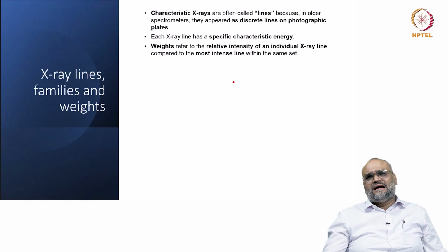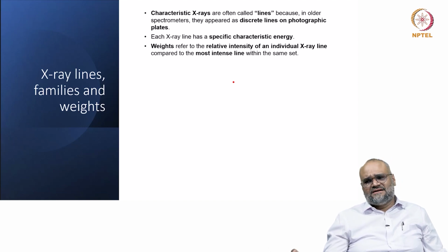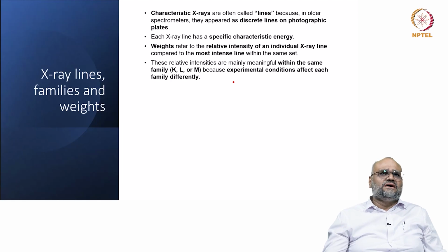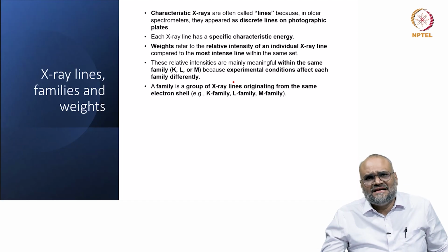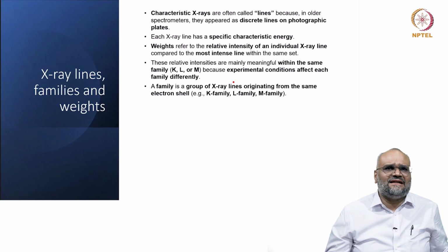And if you look at the area under the peaks of each of these characteristic lines, and if you look at the relative proportions of the equivalent weights that are proportionate to these intensities, you can use this through a simple proportionality relationship, and whether they are coming from which kind of a shell from a specific atom, you can quantify, and this is actually called quantitative EDS mapping or EDS spot analysis.